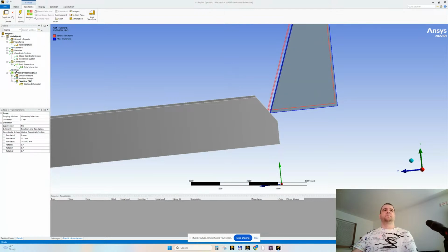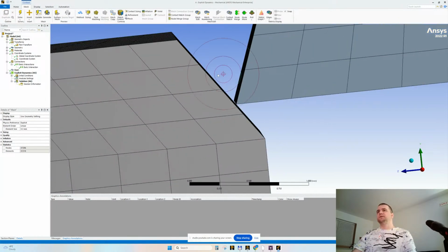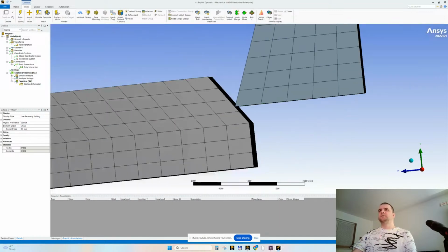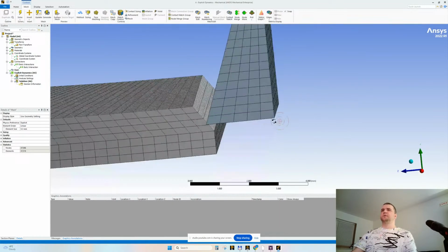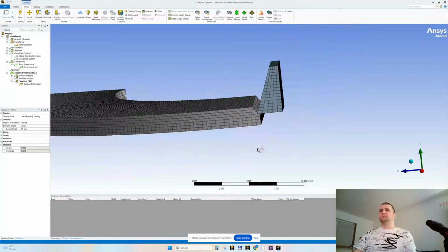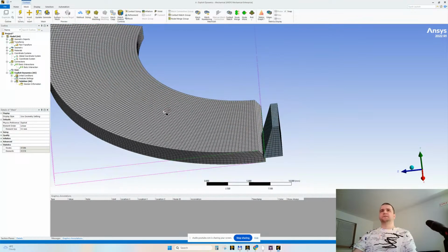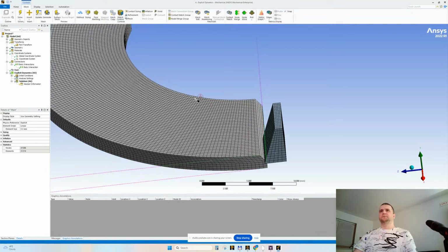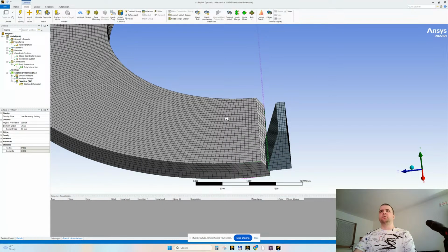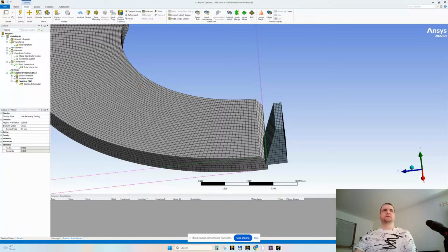Right-click transform, and we will see the mesh. This is the mesh. Something like this. So in principle, the top 3 layers will be shaved. I think the workpiece is too fine regarding the mesh. This is why I wanted to have an annular ring instead of a disk of a solid profile. Let's see how long this simulation will take, even though it's too fine for my taste.